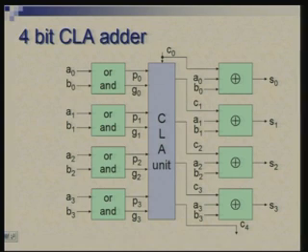First of all, let us understand the circuit which will do this. We have the first stage, which I have captured in these green boxes. Each one of these contains basically one AND gate and one OR gate. The AND gate generates GIs and the OR gate generates PIs. So, we have these P's and G's computed out of A's and B's.